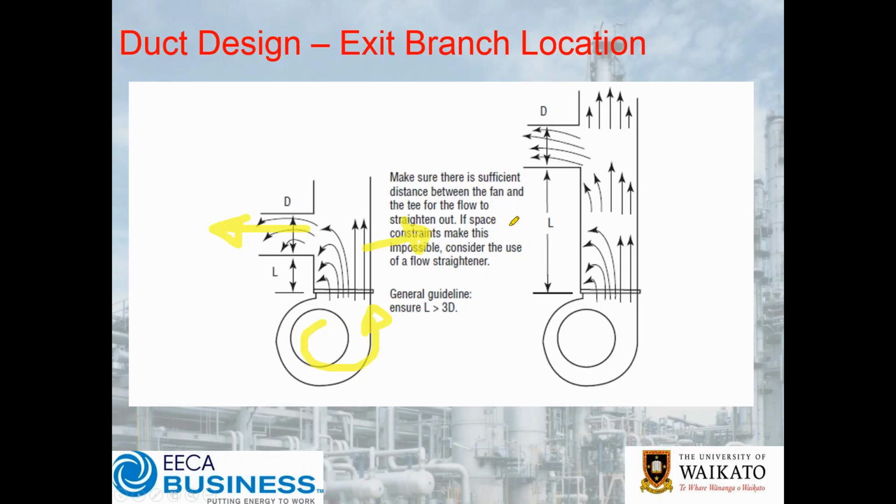So at least in this situation they've got the offtake going the correct way as opposed to the incorrect way, but ideally you want to be further away so that you've got time for that flow coming off the fan to even itself out. Generally speaking, the amount of air on this far side here is going to be a lot higher than on the inside, and so you do need to be careful. You can get quite uneven distribution of airflow.